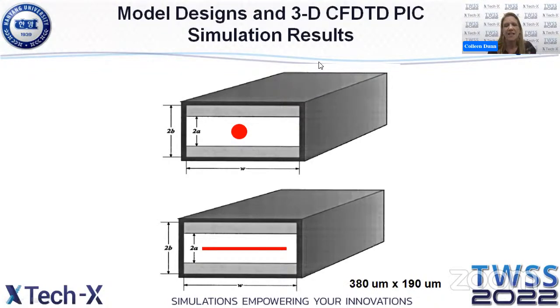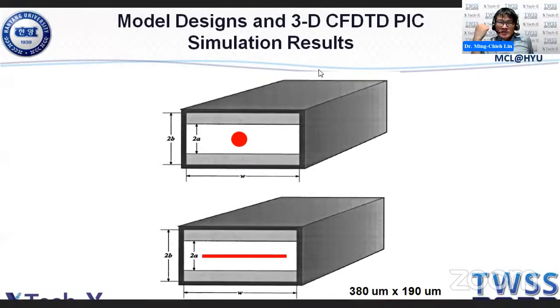We have another question that says, is the dielectric material frequency independent? Actually, in reality no, but this is very complicated. This can be implemented in the simulation as well, but for the preliminary study, we assume it's constant within this frequency range. But you are right, dielectric material is frequency dependent. You can look for the dispersion of this material, but in the terahertz frequency range, studies are very few, especially for characterizing these materials, because a terahertz source is expensive, and determining the dielectric function is even more expensive.